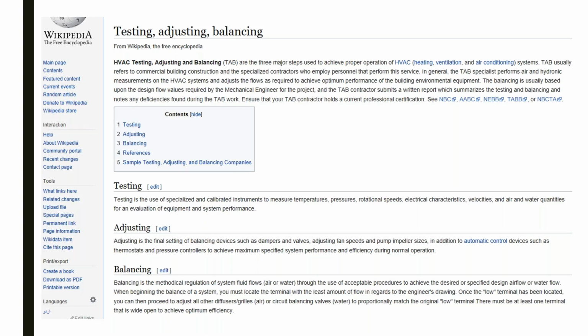So this is where, let's get to what I'm stumbling on. Let's say you're doing TAB for retro-commissioning, and that's really my focus. And you do these measurements and you realize, okay, nothing is to design. Now, a lot of TAB companies, I think, and tell me if I'm wrong, Chris, they would say, yeah, look, we need to make some adjustments. It doesn't match what the mechanical designer came up with. That's what some of them are going to adjust it to. Is that right? That's true.